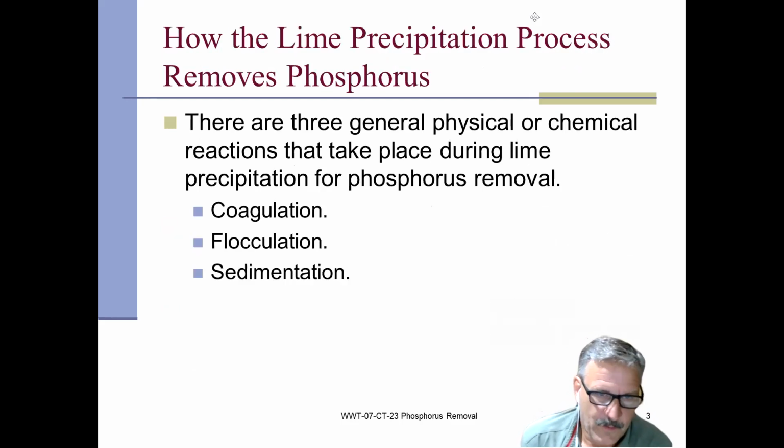It's important, whether it be phosphorus removal or anything else, to understand coagulation, flocculation, and sedimentation. There may be some questions related to those things. So I'm going to touch on those just briefly this morning. Coagulation is when you add a chemical, whether it be alum or something else, or some kind of polymer to a system. So when you initially add the chemical and you're mixing it up, that's your coagulation component.